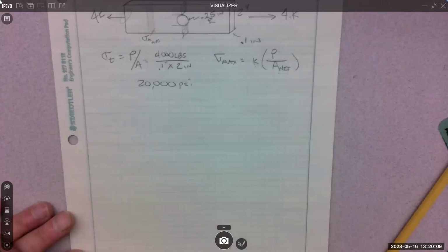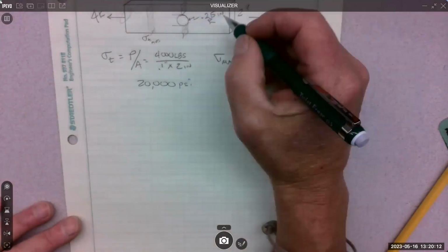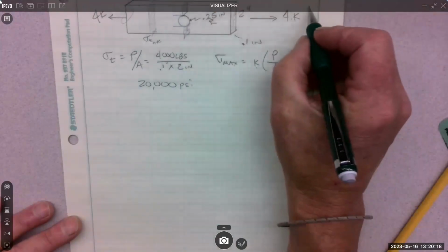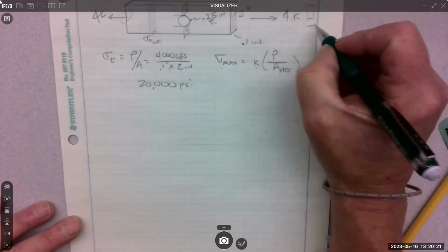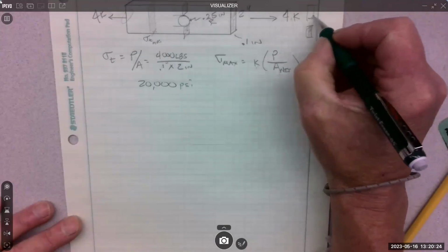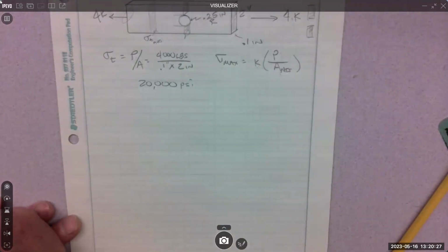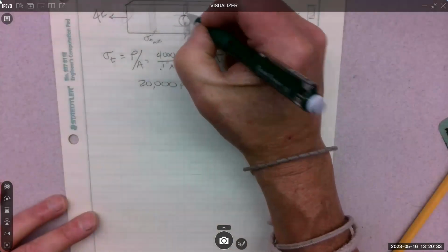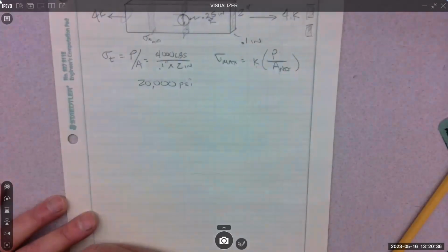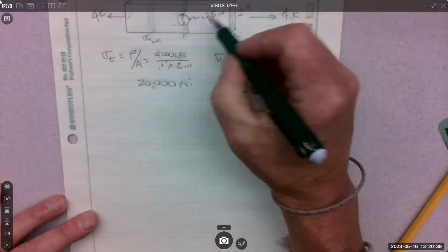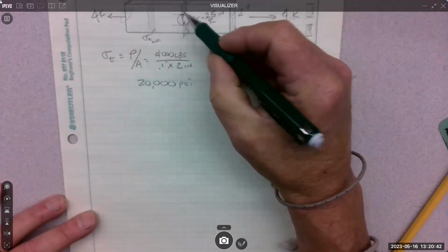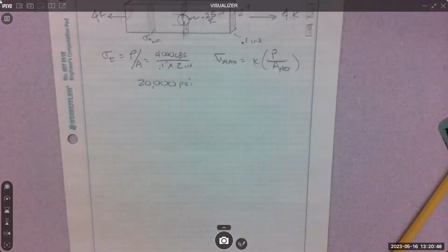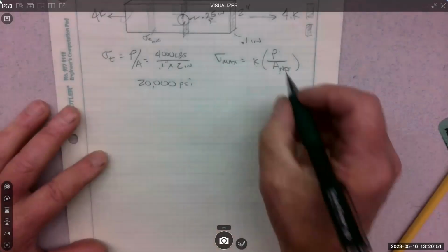So if you were looking at the cross section, you wouldn't see the circle. Yes, exactly. So here's the cross section for average, and the cross section for the concentration would be that. The hole's removed, so you pull out this dimension when you calculate the area. Instead of the full length, it's going to be 2 take away 0.25. This and this add up to 1.75 times the thickness. Does that make sense?